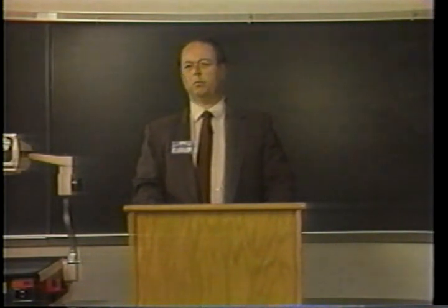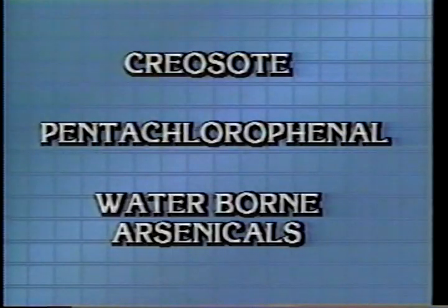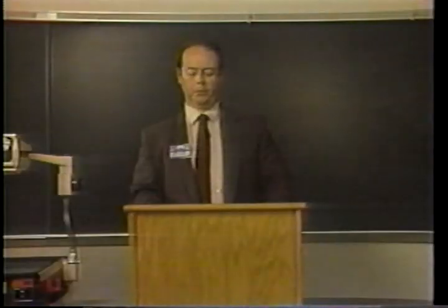The three basic wood preservatives which we are talking about are creosote and its solutions with coal tar and petroleum, pentachlorophenol and oil, and the waterborne arsenicals, which include CCA, copper, chrome, and arsenic, and ACA, which is ammoniacal copper arsenate.